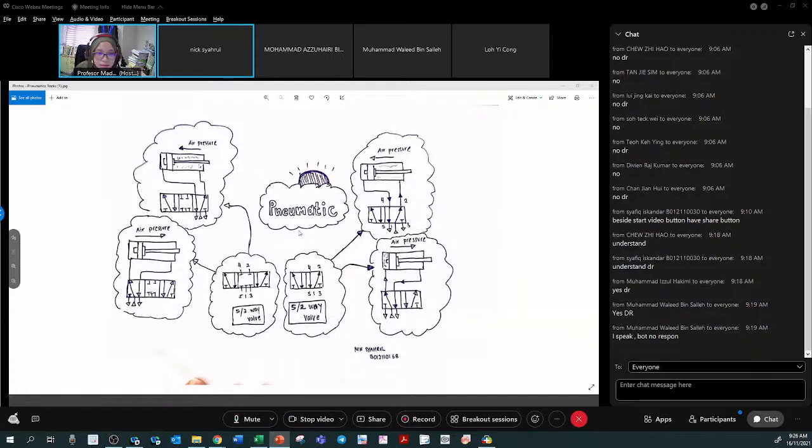Okay, looks good. So looks interesting, this figure. Can you explain one by one if you want to explain everything. But if you want to explain 5/3 pun okay. If you can see here, this is a 5/3-way valve, and this is a 5/2-way valve. If you see the diagrams, it looks a little bit different. 5/3 has 3 slots here, and 5/2 has 2 slots.